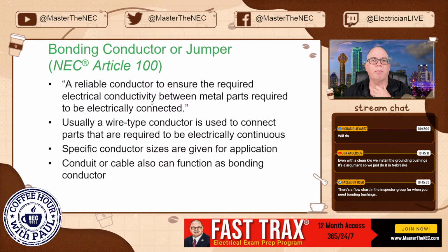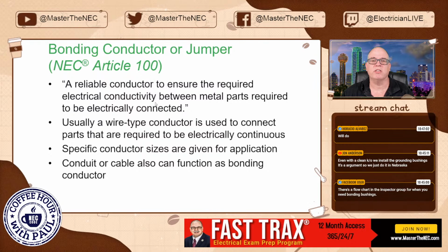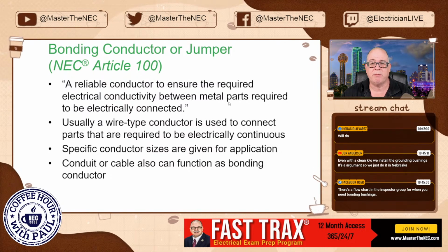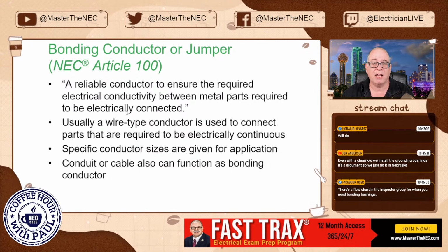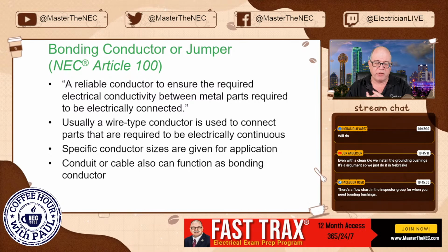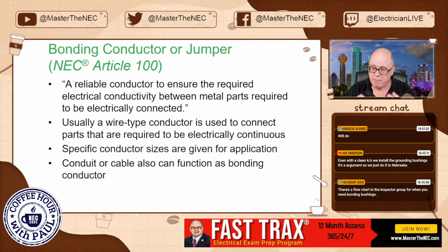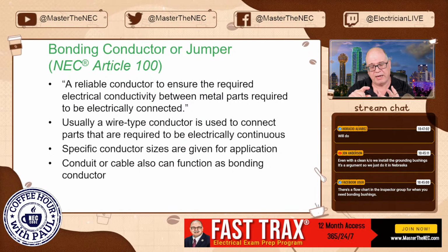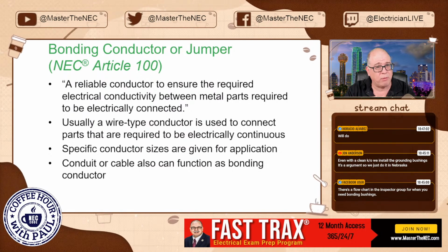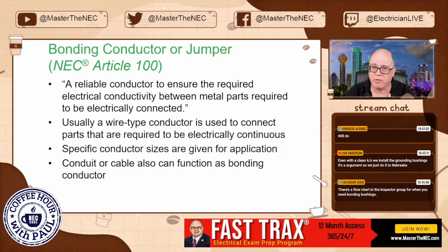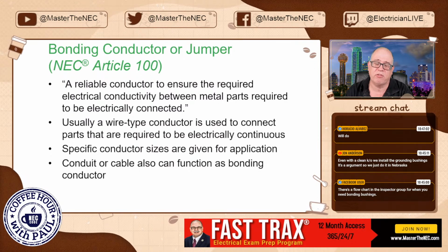Bonding conductors or jumpers: a reliable conductor to ensure the required electrical conductivity between metal parts required to be electrically connected. Bonding conductors or jumpers come in various flavors. Main bonding jumpers, they're still jumpers. We have jumpers that cross over, like water meters. We'll have all kinds of different types of jumpers. But the main concept of these is what?